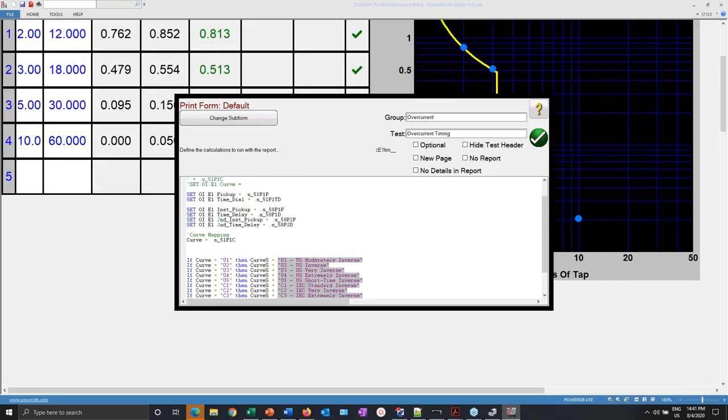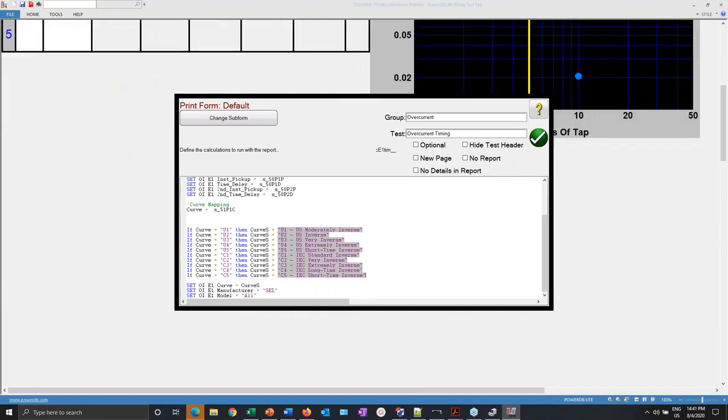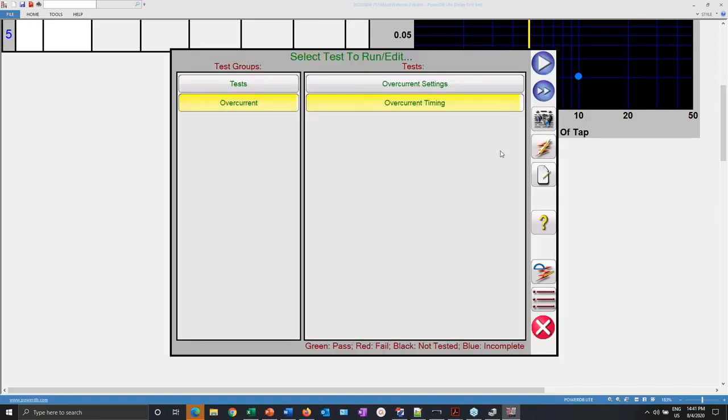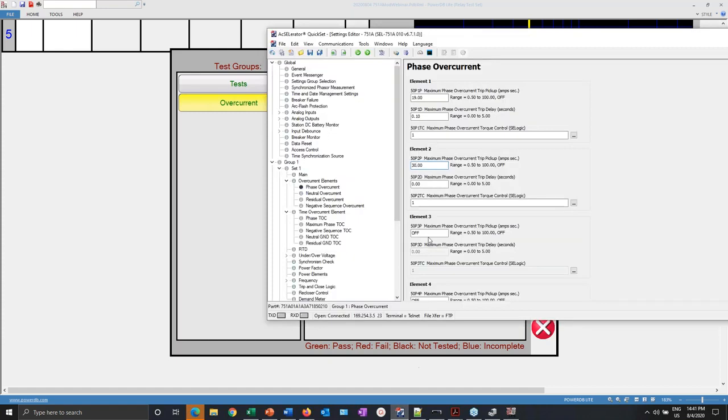So this is, I would say, the only thing a little bit fancy that we had to do, but it's not that fancy. I believe that anyone can do this type of coding today. It's just if the curve equals a U1, then the actual curve that I'm going to use is U1 moderately inverse. Now, this code will work, and now I can go ahead and do the same thing.